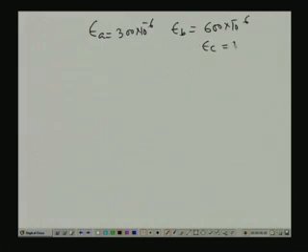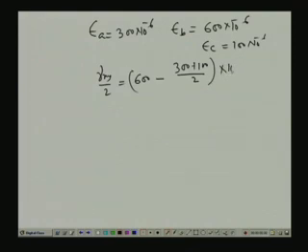Now, the value of epsilon A is equal to 300 into 10 to the power minus 6, epsilon B is equal to 600 into 10 to the power minus 6, and epsilon C is 100 into 10 to the power minus 6. Now, gamma xy by 2 is thereby equal to 600 minus 300 plus 100 by 2 into 10 to the power minus 6, which is 400 into 10 to the power minus 6. Now, we plot these in a Mohr circle, where epsilon A is epsilon x and epsilon C is epsilon y.